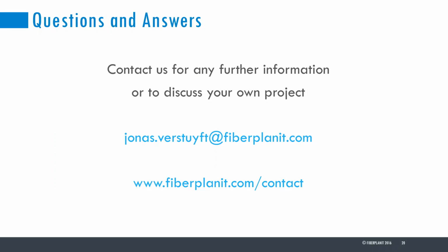Another question. How do you know from the map information which properties are private, or where you will have some troubles digging or placing fiber? Yeah, that's a good question. This is basically something you can indicate with the fine tuning of the software. We saw in the design rules that you can indicate the cost of standard trenching, but there's also the possibility to indicate per street or possible route which subtype it has, and there you can indicate whether it's maybe private trenching or not, and then you can exclude this from the design.